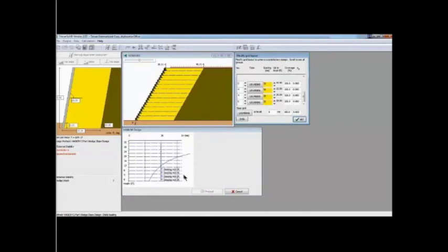Now we see this HA6894 window down here at the bottom is slightly different than what we've seen on the retaining walls. This is no longer a stress curve that we're trying to make our geogrids come to the right of. Now this is a spacing curve of the geogrids that are in the design. So the modified grid layout screen here is very similar, it is exactly the same as the retaining walls.